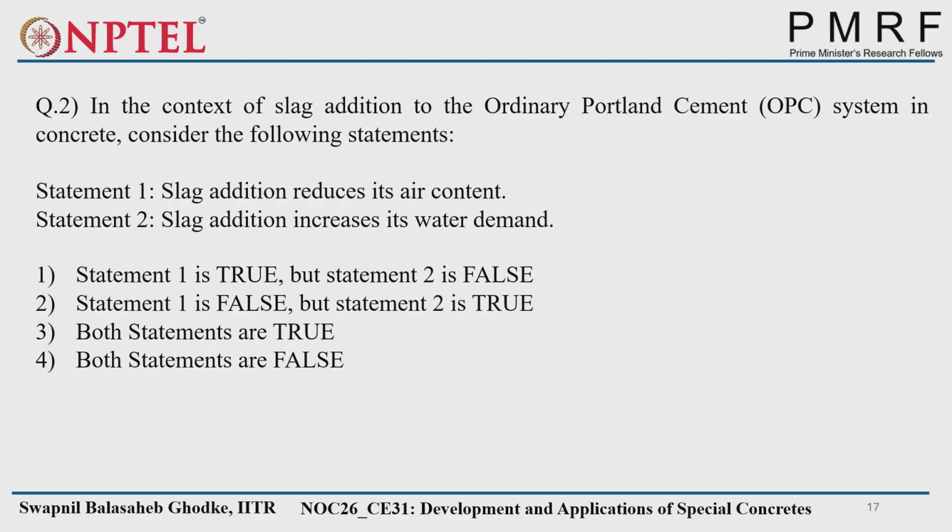Next one: in the context of slag addition to ordinary Portland cement, Statement 1 says slag addition reduces its air content. Statement 2 says slag addition increases its water demand. So what will be the answer?